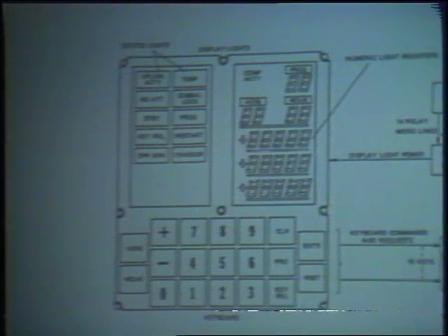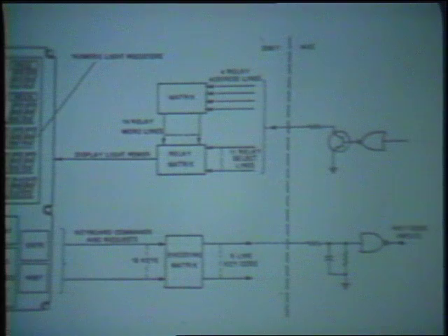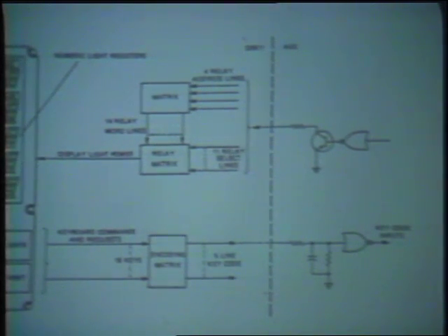Electroluminescent lights were used in the DSKY since they are small, easy to read, and required relatively little power. The lights were driven by 250 volt, 800 hertz from an amplifier in the DSKY with the gain or output amplitude controlled by the spacecraft light intensity control. The display is switched under computer control by miniature latching relays in this group here, whose contacts are used for the decoding logic between the computer's 5-bit binary data and the 7 light segments of each decimal digit in the display. In addition, the latching relays provided memory with no consumption of power following the switching action.